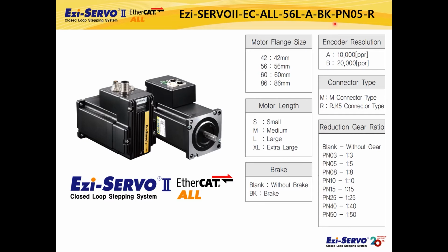BK means that a brake is attached on the motor, and PN05 means that a planetary gearbox is attached on the motor. You can select the motor from a NEMA 17, 42 mm size motor to a NEMA 34, 86 mm size motor. The length you can select depends on the motor size. The encoder resolution can also be selected as shown in the table. R means RJ45 connector type. There are 2 types of connectors, M connector and RJ45 connector.